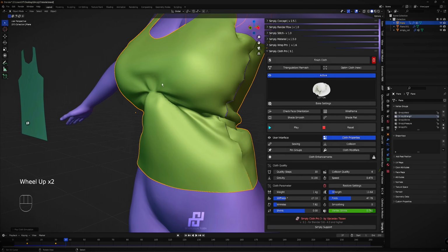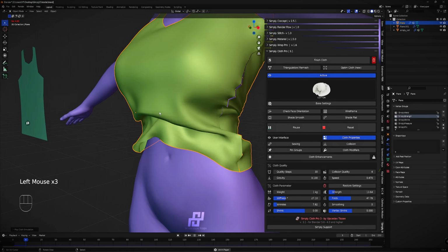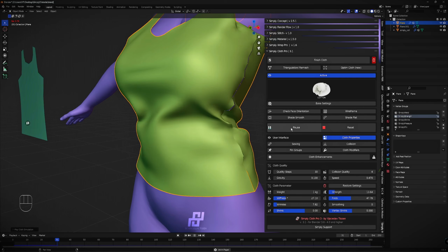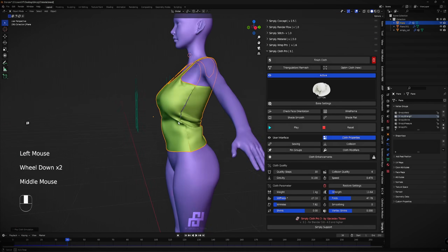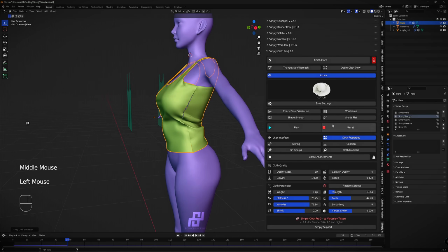I don't want to have this shrinking value, so I go to this vertex shrink parameter and clear the keyframes and set it to 0. So it will not shrink anymore at this point. So we have a basic regular cloth with fewer wrinkles, I see. So you see it is leatherish. We need more wrinkles, more stiffness perhaps, and the gravity is too slow. We set it to 1. So the main values and the default values are correct and easy to start with.